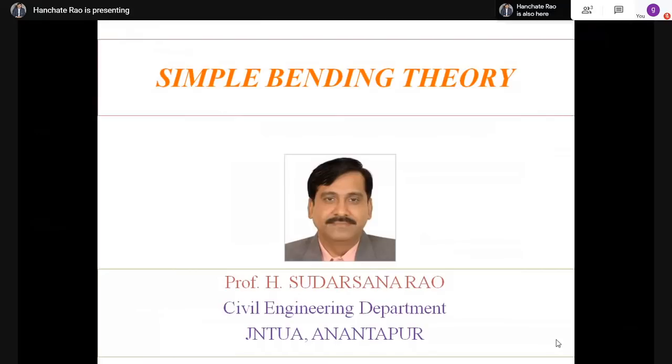So please remember that. Similarly, I have already explained one simply supported beam problem. If you have 2 point loads acting at L/3 from each support, in the middle third portion, there is no shear force, there will be only bending moment. So that is again a pure bending case. So these are the examples of pure bending.